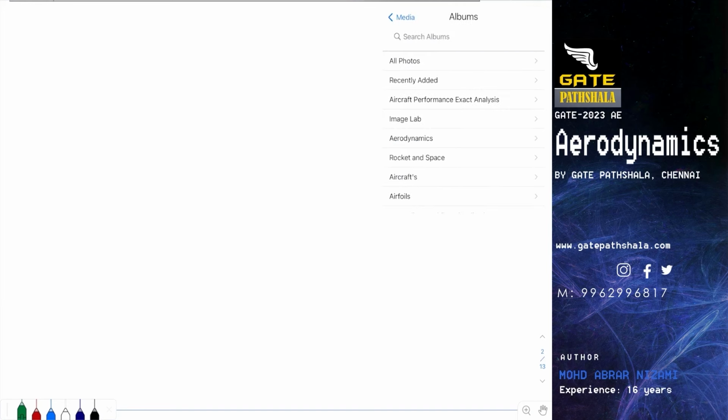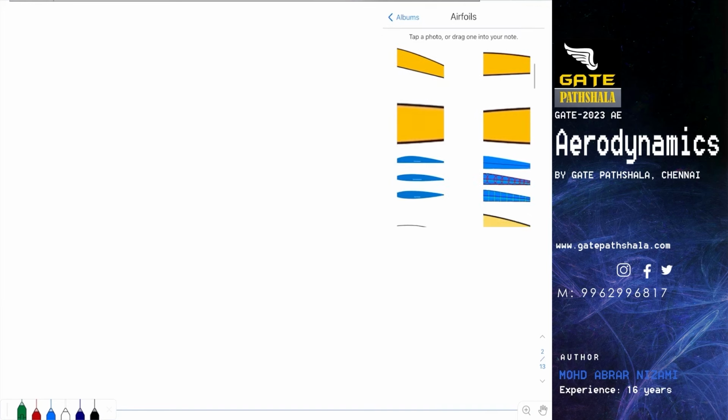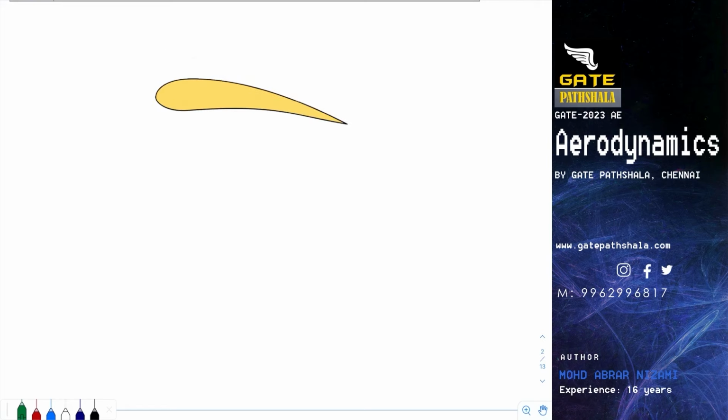basically used to be able to evaluate the exact magnitude of the circulation imparted on the surface of the aerofoil so that the flow will be leaving the surface smoothly. So suppose there is a flow taking place over an aerofoil like this.